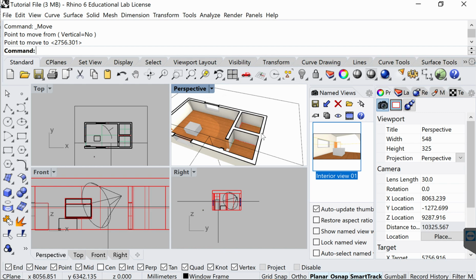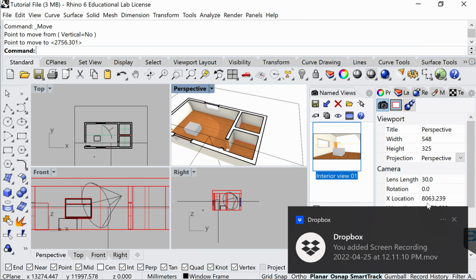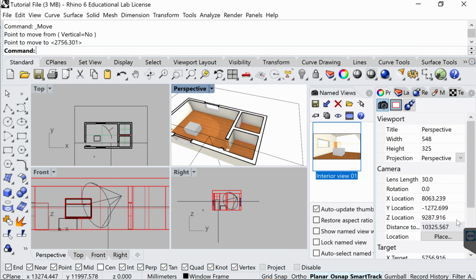And to understand that, please refer to the Photoshop tutorials that were already uploaded before and go through them to know how we can add the hatch, for instance. Right now it's a white hatch and we want it to be black or gray. You can add figures and silhouettes of people inside, and this is what you should do. You can also add scale references such as a tree or car or a surrounding environment on Photoshop, just to make things look more in perspective and more realistic and to give us a better experience of the space.